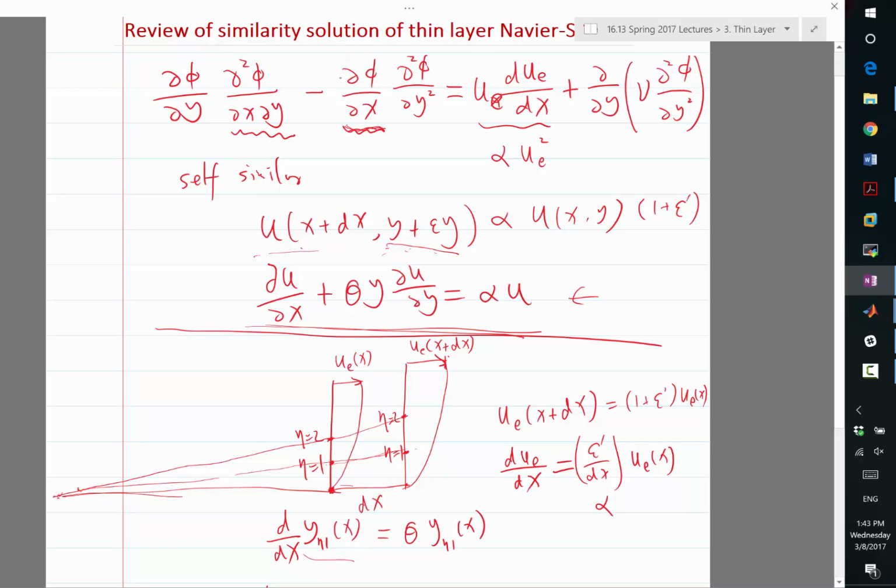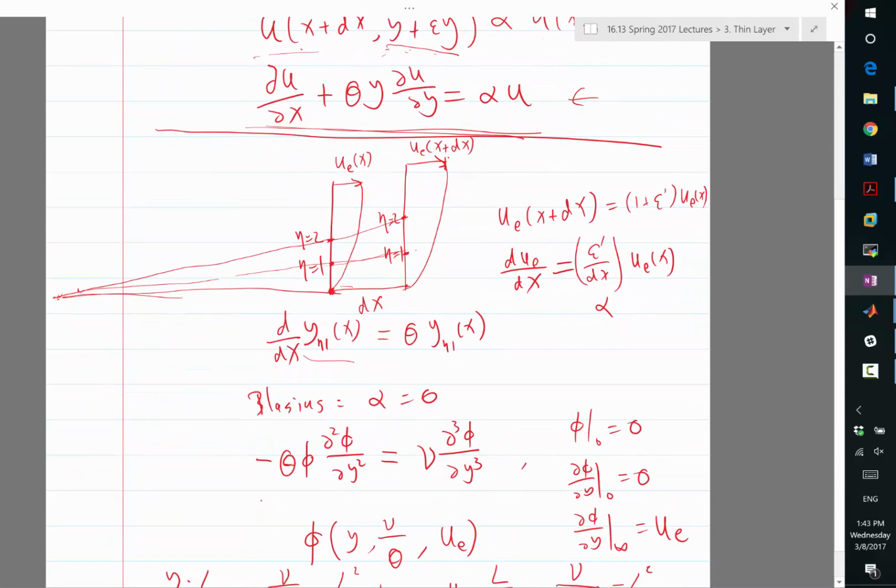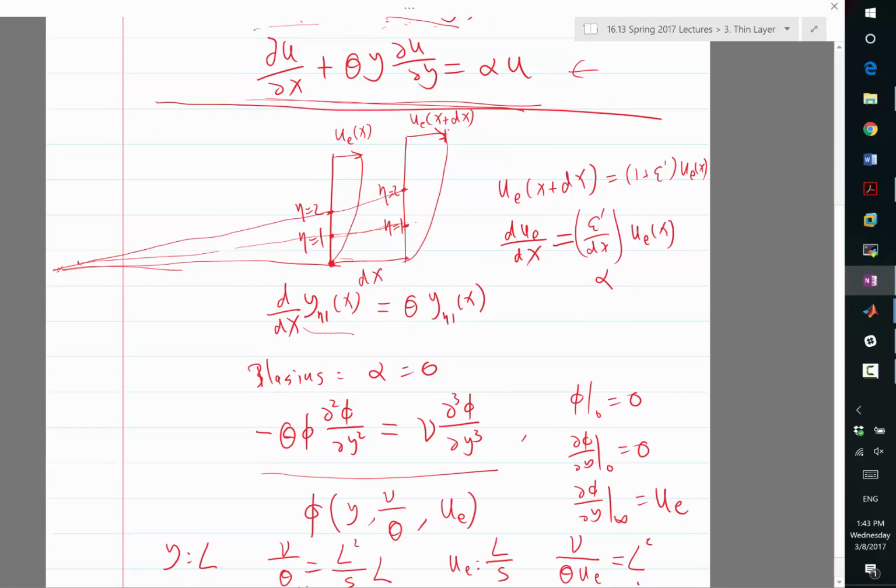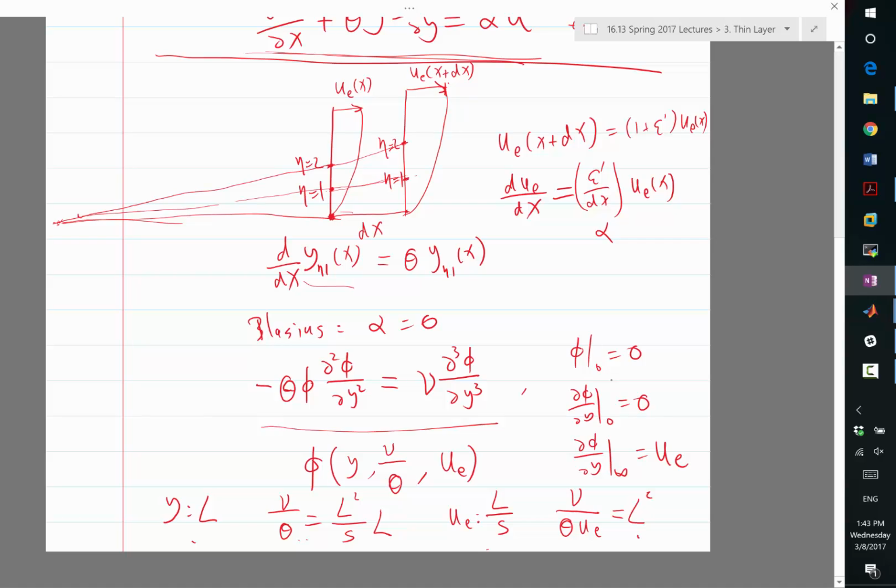So when we are getting rid of this, d phi dx equal to 0 at the wall is used. As a result of using that, the equation we got has no x derivative in it. So it's not even possible to apply that boundary condition in this equation anymore. We only have a chance to apply the x velocity equal to 0, which is d phi dy equal to 0. All right. Okay.